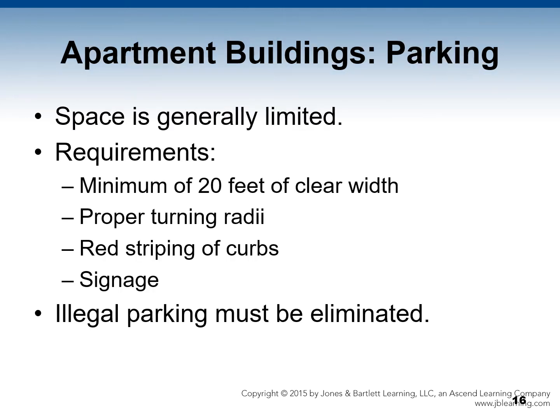With parking, space is generally limited. Requirements include a minimum of 20 feet of clear width, proper turning radii, red striping of curbs, and signage. If you drive around and look at properties, 8 out of 10 times this is not designated properly. If you're lucky, they've got a fire lane and a fire curb marked off in red. The owner is responsible for making sure that illegal parking is eliminated, but they don't often.